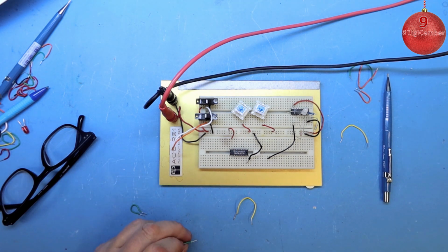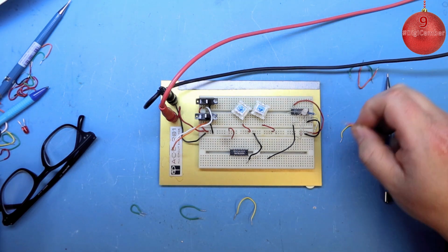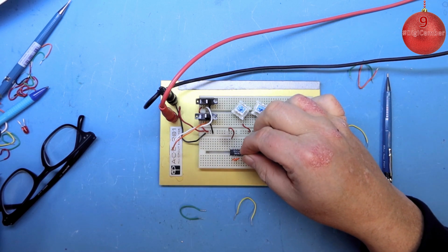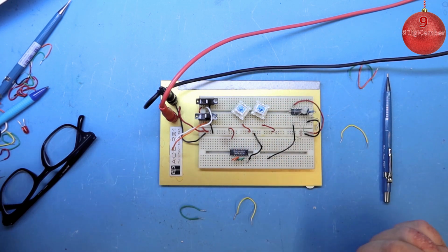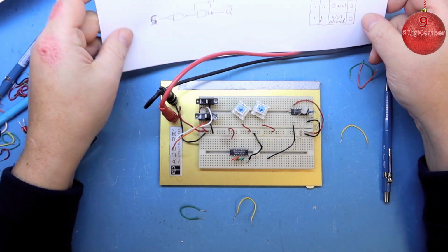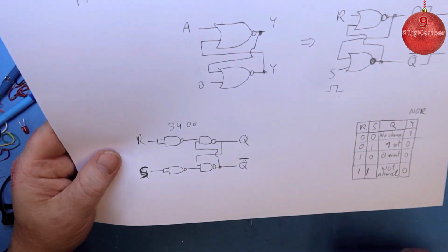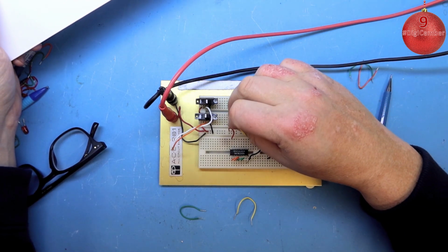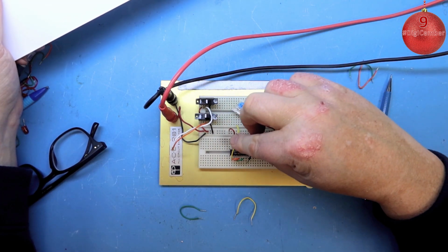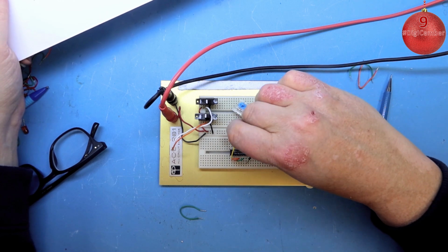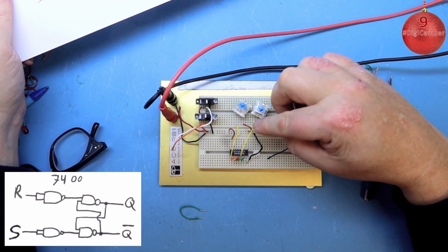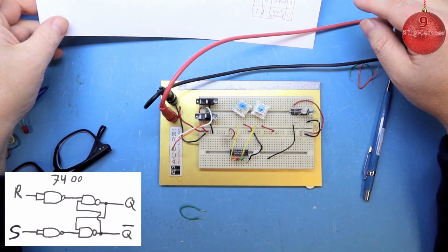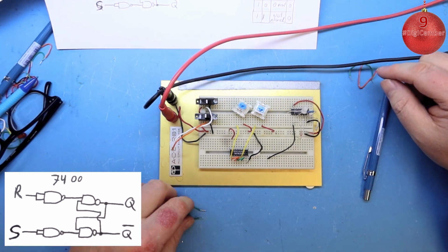And that also means that I'm going to connect the two gates on this side, both the inputs together, like so, to make this inverter here. And from one of the switches, it's going to go like so. And from the other of the switches, it's going to go like so. Now we have connected the inputs here, and now we are just going to connect up this other block.